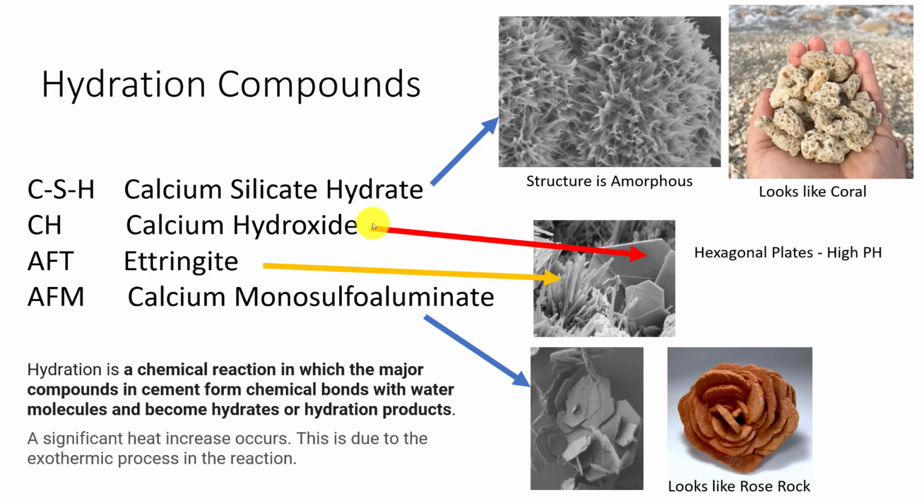When we put steel in concrete, it would want to rust and corrode. If it's encapsulated in the concrete and sealed by the concrete, it will not corrode, because iron hydroxides form due to the fact that the pH level of the CH here is going to be very high. We're talking 12 to over 13 on the pH scale. You had chemistry where you talked about acids and bases, and yes, both of them can cause a burning sensation. So when you're in the lab and you have the concrete, you might sense that if it comes in contact with your hands because of that high pH. So be sure to wash your hands properly.